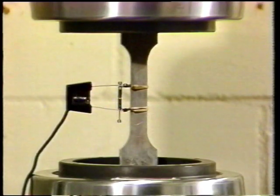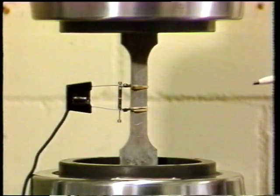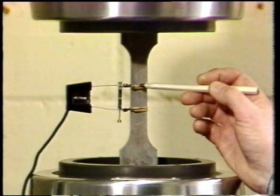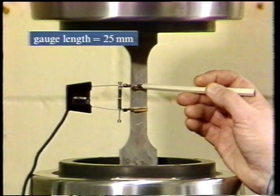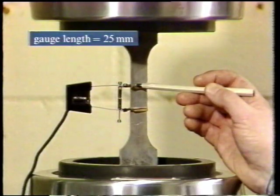Well, the answer is to use a sensitive extensometer attached to the uniform part of the gauge length. Right, well, here's the specimen set up for your test. We want you to plot the force extension diagram. We've got the extensometer attached to the gauge length, and it's covering a 25mm length of the parallel gauge portion.